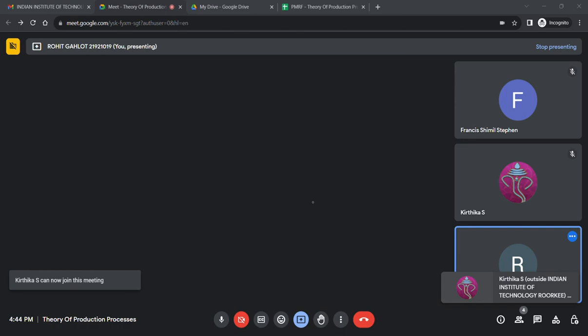From here you will find out the value of K, right? Now the K value will be coming around 0.04013. Now you will use this value to calculate when your solidification time is 3. So you will write it as T solidification is K times (V by A) square. So this will be your 3 times K, your D value is 0.0518. Yes. The unit, can you tell me the unit? Meter. Yeah, right.